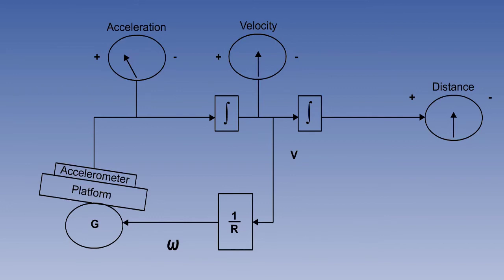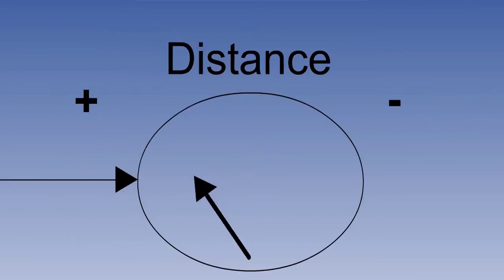The whole loop has oscillated one full cycle to return to its initial configuration. It will continue to oscillate in this manner until the INS is switched off. We have had an apparent change of position and then a return to the original position, even though the aircraft has not actually moved. This type of periodic error pattern is called a Schuler oscillation.